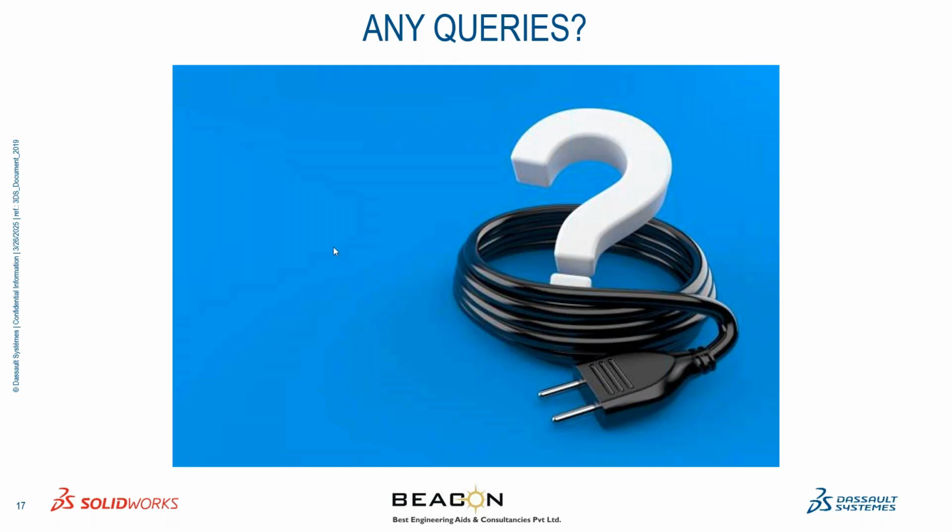Yeah, so there is something called voltage drop also. This is only going to be calculated based on the inputs that are provided. So if you give a particular voltage, and there is a particular design rule check called voltage drop, it will find out if there is any voltage drop and list it out for you. That's about it. But the input should be provided from your end, because there is no simulation of any sort for electrical circuits here. So it is just purely a design software. But we can give certain inputs and manipulate them to get our desired outputs also.